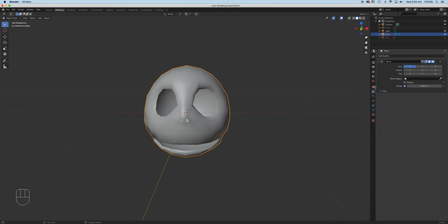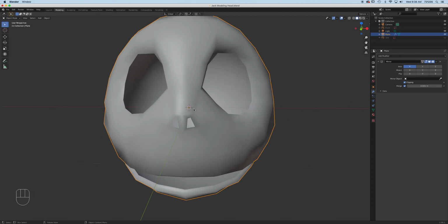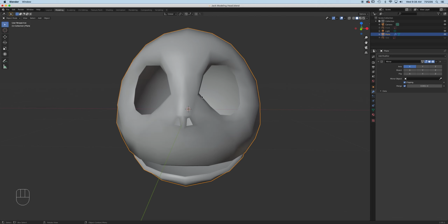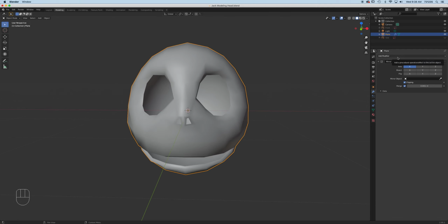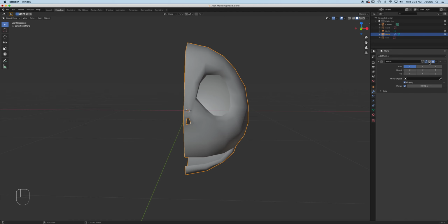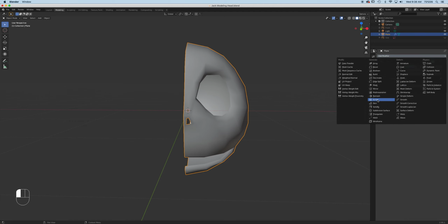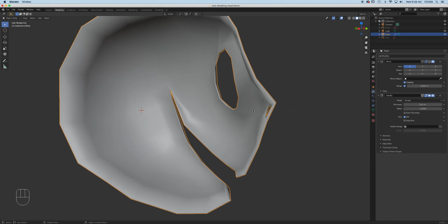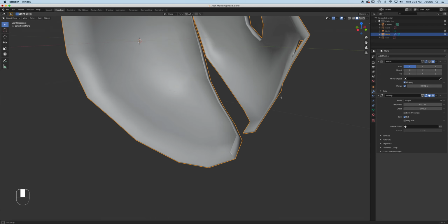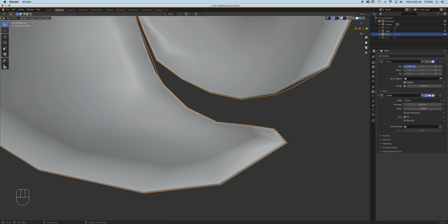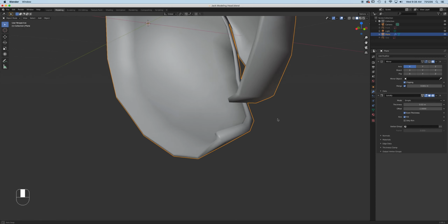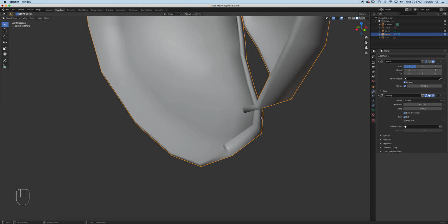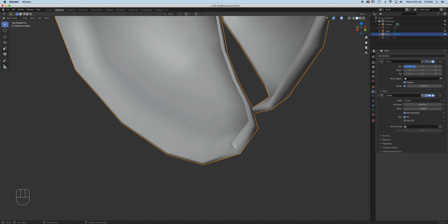So first we need a mirror. We turn on clipping like last time, so any changes you made or manipulated don't cross over the plane right here. And then next, actually let's turn this off temporarily, and then let's add solidify. Solidify simply creates thickness to this. Okay, it's right there, and I can go with even thickness right here, and then just click the arrow one time to kind of double that. What it does, it gives it a thickness. That's it. So it's solidifying